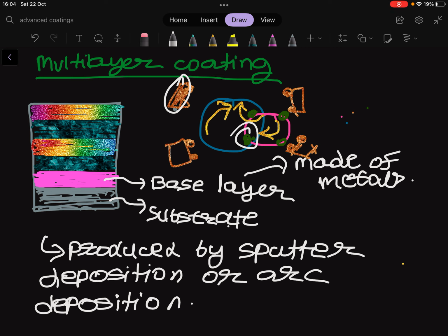For example, let's say our multilayer is made up of a sequence of titanium nitride layer plus aluminum nitride layer. In order to produce this sequence with 4 targets, we have titanium in alternate rectangles and aluminum in the other 2 targets, which are alternate and opposite.